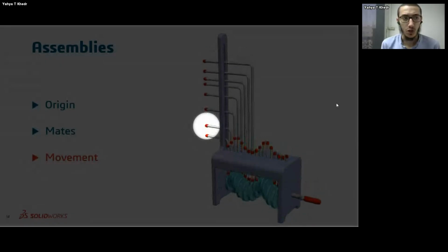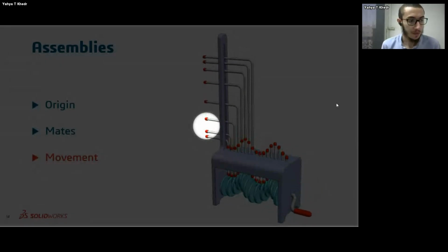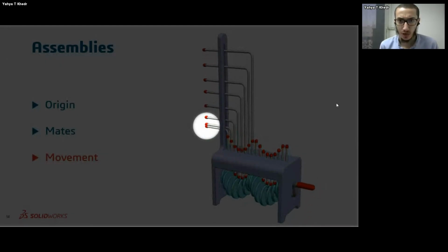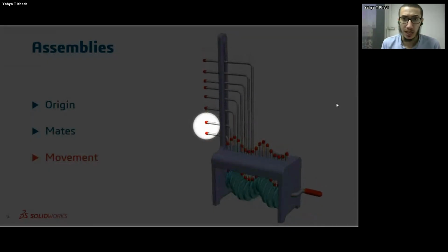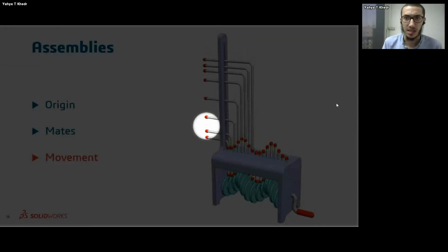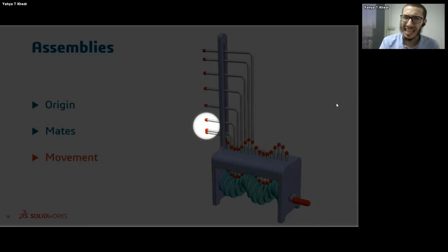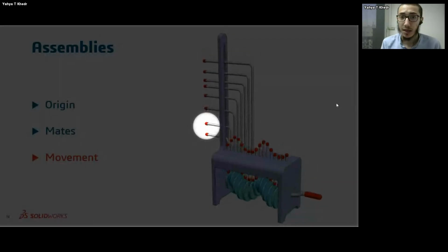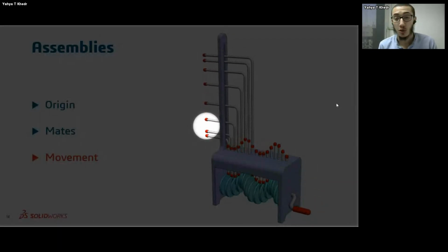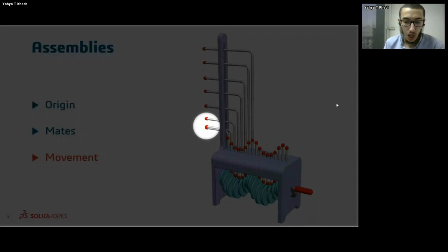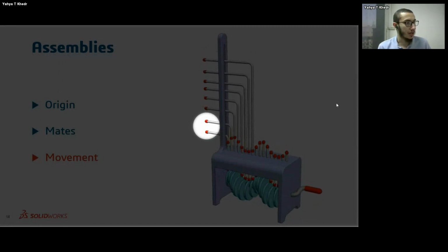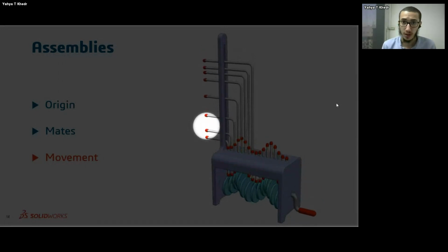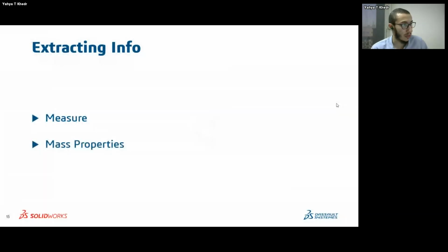And it's really important for you to go through something like that, go through the process of detecting interferences, looking at the reports that come out of the interference and learning how you can modify these, how can you fix these, how you can identify exactly which components are interfering with each other, and based on that, taking the best course of action to modify it or to fix it or to change it, if that's what the question wants. So these are the different aspects that you should consider when going through the assemblies, or for segment 3.